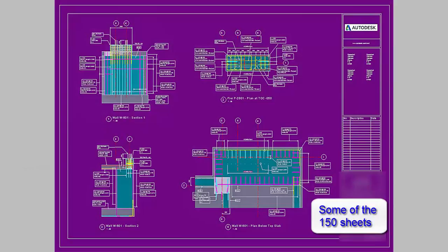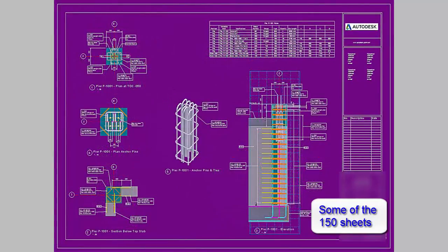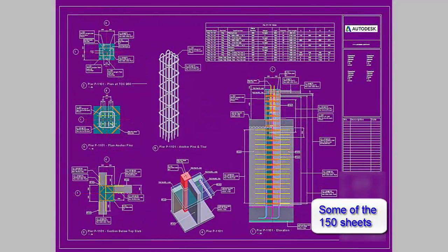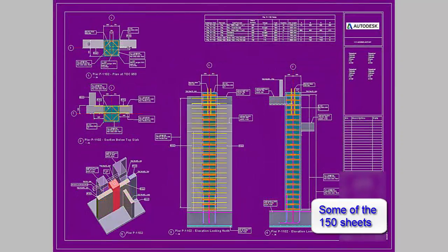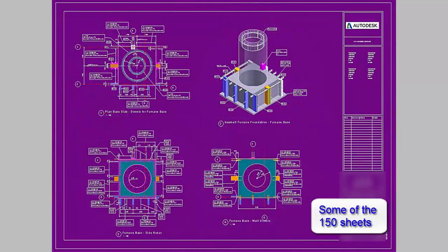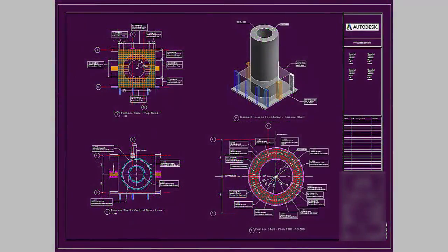This brings me to the final part of this video, rebar schedules. I have organized the rebar schedules for this project so that each structural member of the foundation has its own rebar schedule. This may seem extravagant, but rebar schedules are just so simple to create, as I will demonstrate. Once the rebar schedule template is set up, each rebar schedule can be populated by using a single query parameter.